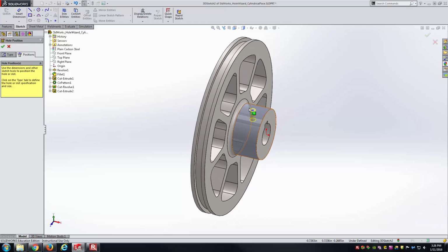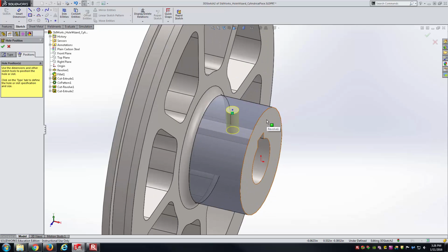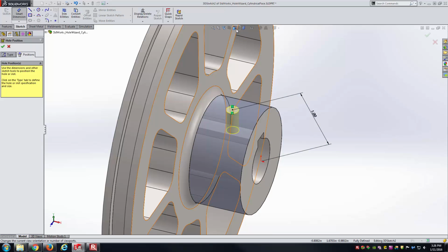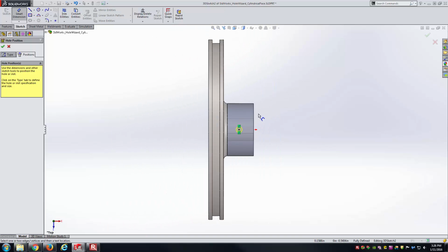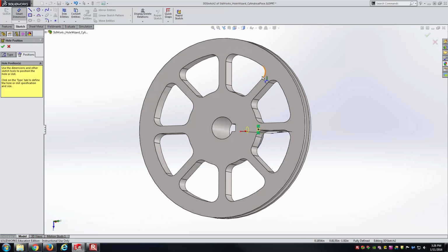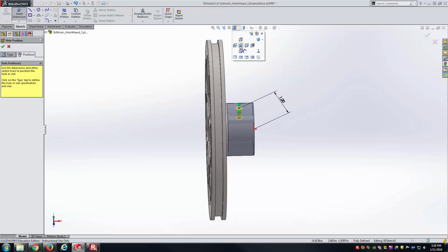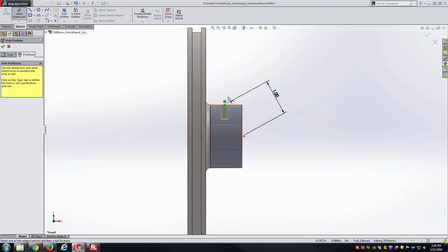And so now I need to specify some offset distance, for instance, from this face. And so one thing you might try to do is place it from the origin. And so here's where you have to be careful, because from the top view, you can't even see it, but from some views that looks fairly close. But if I go over to the front view, it's not what I really want here. It's very unlikely you would see that as the desired dimension on the drawing.